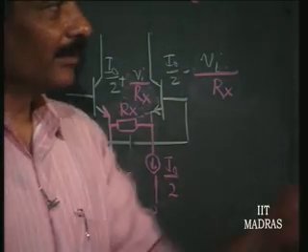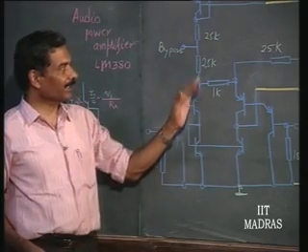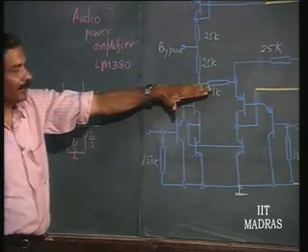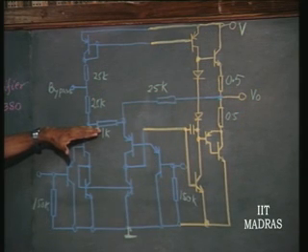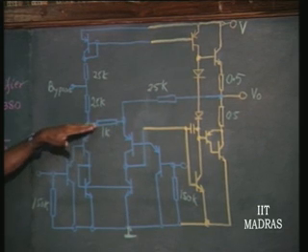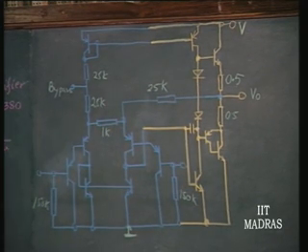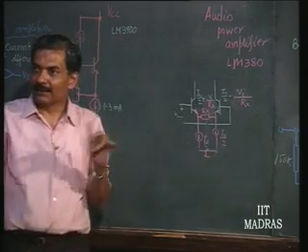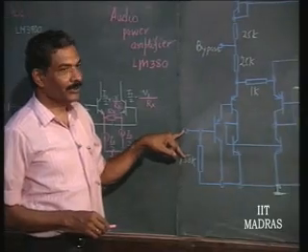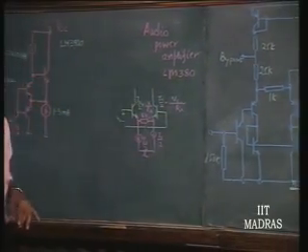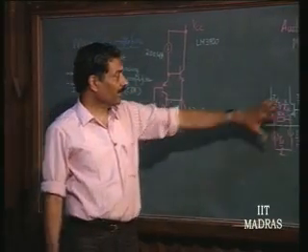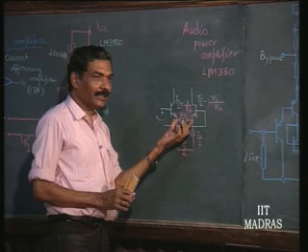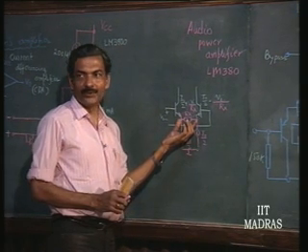Now, you can see this is nothing but a differential amplifier which is perfectly symmetric. Imagine this is 25K, 25K with diode to ground, then there is 25K something else. So, this is the place where the negative feedback is effective to the input stage. You can see if you are applying an input at one point, to the other point you can give the feedback. So, the actual input to the amplifier is the current input minus the feedback voltage. That is how you can adopt a strategy like this using emitter degeneration resistance. So, it is no different from the differential amplifier, except that a physical resistance occurs coupling the two emitters.